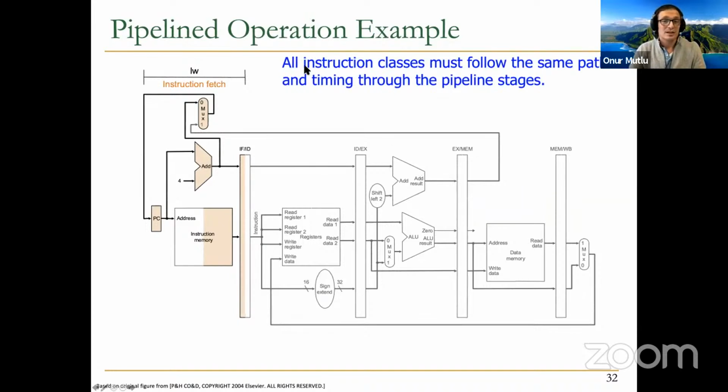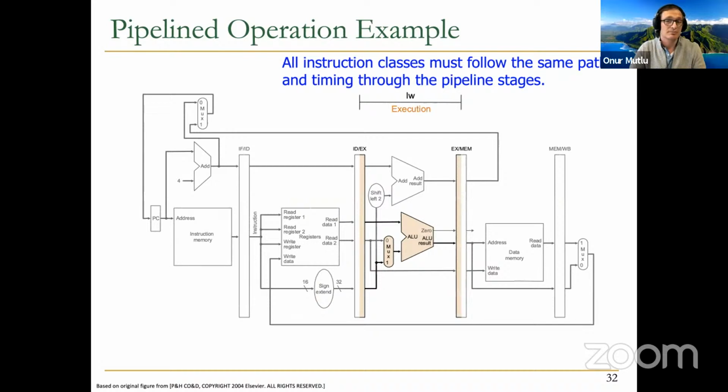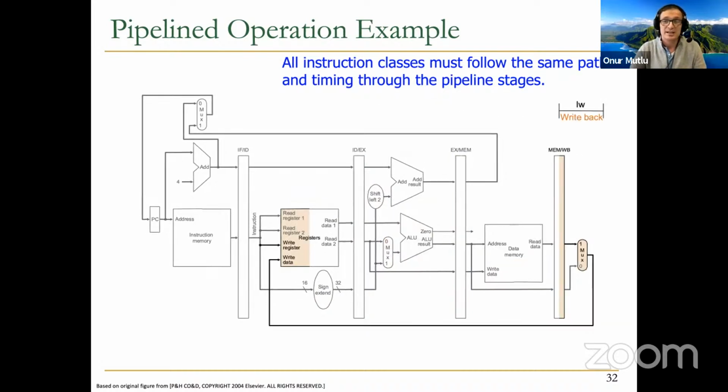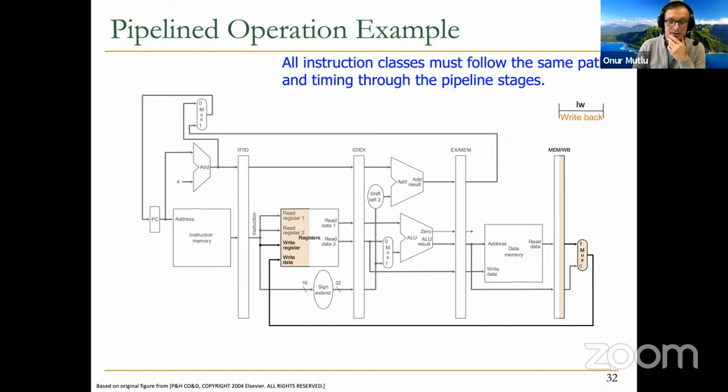Okay. So all instruction classes must follow the same path and timing through the pipeline stages. So this is instruction fetch, load word. When the load word is doing instruction decode, it goes through execution, it goes through memory, it goes through write back. So load word actually exercises all of them, right? Remember, load word is the culprit. It exercises all things in a processor, if you will, and it exercises all things in a pipeline. But that's not necessarily true for an add instruction, right? So also remember that.